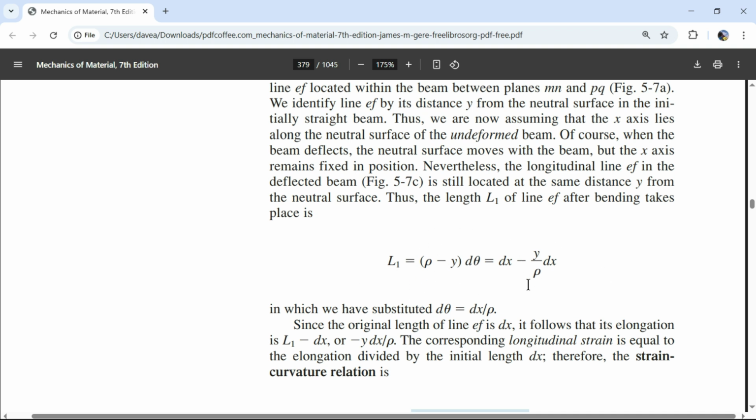just the equation that you have to come up with on your own. Derive it yourself; there are a few methods to do that. I like the guess and check first. Throw in a value of 0, and what should the length be? Well, rho d theta. It should be dx, and that's the same thing. Rho d theta is dx. Radians times radius is arc length, and the arc length is dx. So if I throw in a value of y equals 0, then the length is dx.